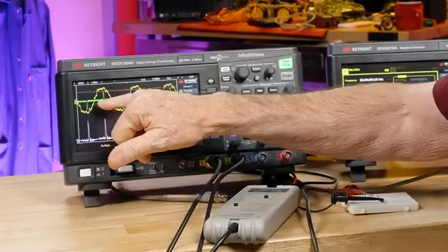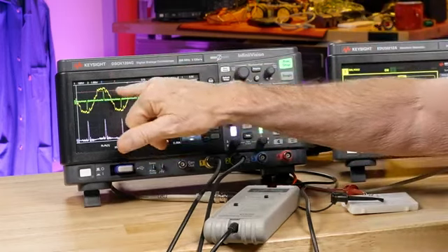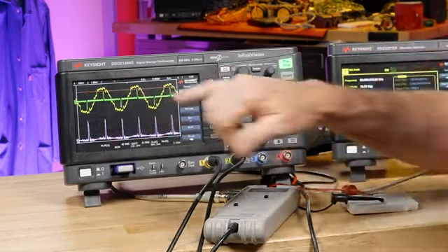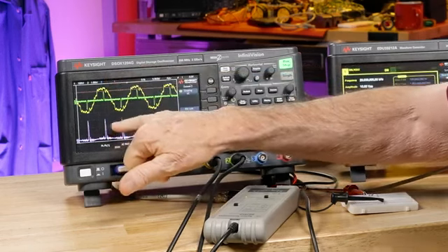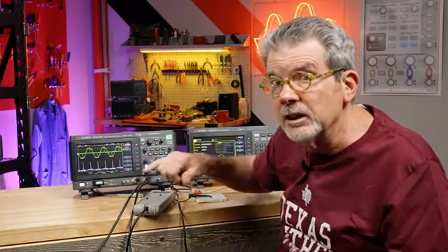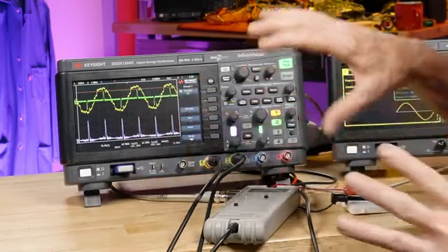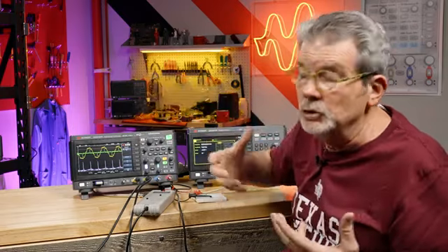Now, what I want you to notice here is that when the voltage goes positive, the current has a positive peak. When the voltage goes negative, the current has a negative peak. But when we multiply the positive current times the positive voltage, we get a positive power. And when we multiply a negative current times a negative voltage, we get a positive power. It's always producing positive power pulses. The power I'm measuring on this device right here is never delivering power, it's consuming power.